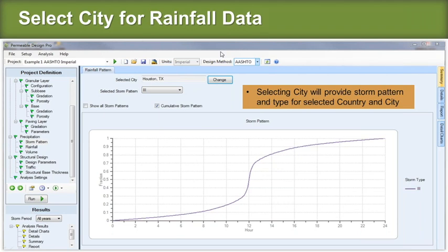And with time, I mean, you may get some reduction of the permeability of the surface because you get some materials in there, and you go out and you test this. There's ASTM standards for the tests. You measure the permeability. You can come back to the program and put in the actual and see, is it still good enough to handle the storms that I want it to handle? So it's an iterative process that really works quite well.